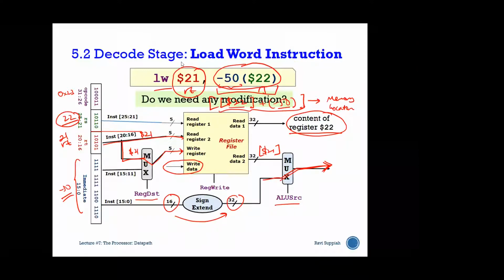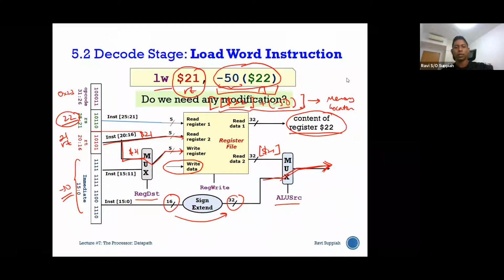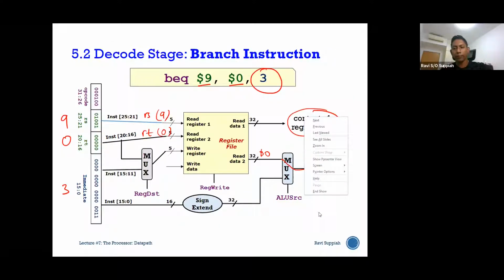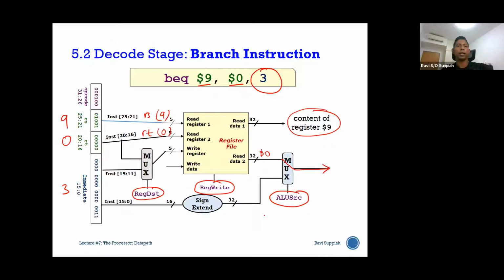My other question is, how do we program the multiplexer? How does the multiplexer know? Correct. The multiplexers are all controlled through various control signals, and these control signals are generated by a control block. That is actually the next chapter. There are many control signals we will see later on as well. These control signals are very important because they decide how data will channel through from one stage to the next stage: which data is selected and where it goes to next.